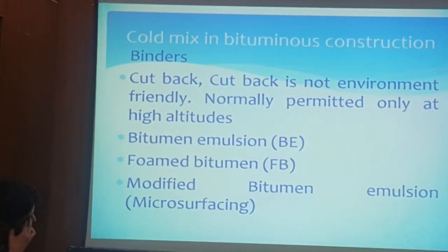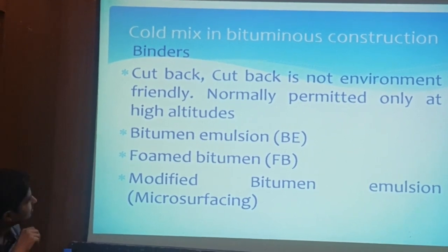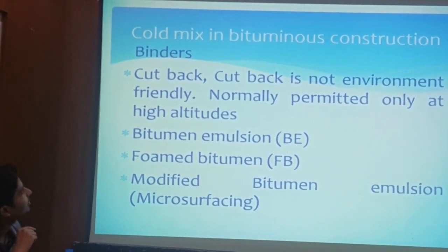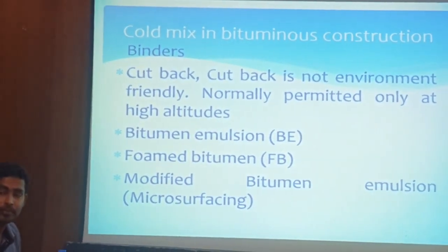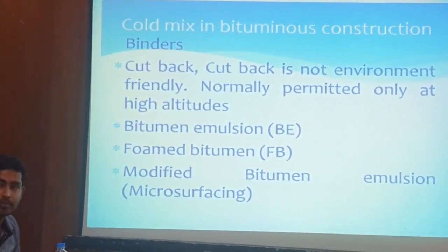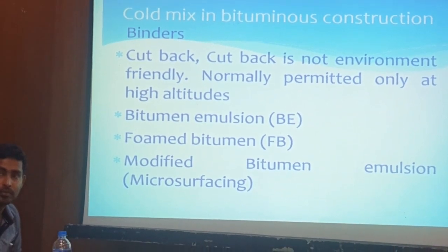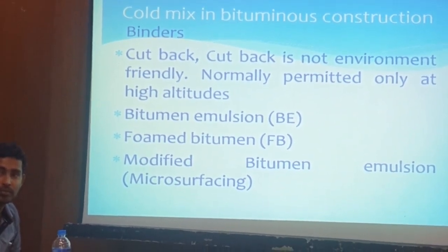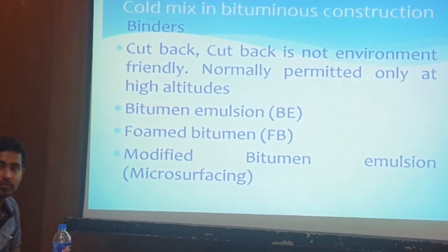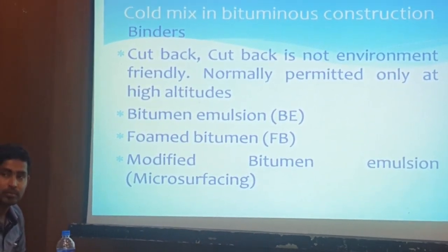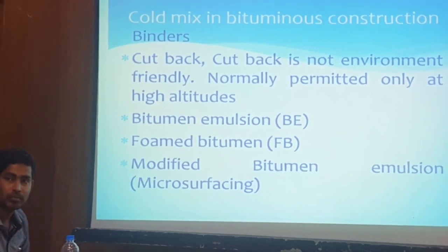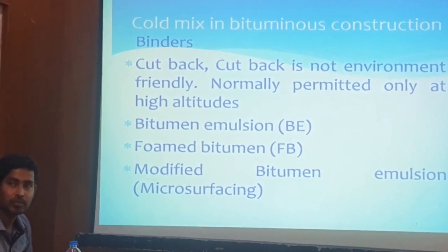You know about foam bitumen? Anybody have any idea about foam bitumen? It is just an air jet being passed, and on the other side hot bitumen is passed. It is a sort of foam, the volume expands 15 times more, and it can cover the aggregates much better than normal emulsion. So that is the advantage of foam bitumen. But handling is an issue.